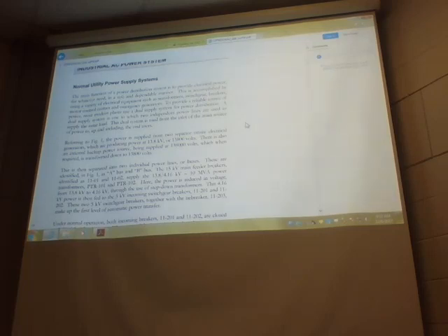So the main function of a power distribution system is to provide electrical power for whatever need in a safe and dependable manner. This is accomplished by using a variety of electrical equipment, such as transformers, switchgear, breakers, motor control centers, and emergency generators. To provide a reliable source of power, most modern plants use a dual supply system for power distribution. A dual supply system is one in which two independent power lines are used to supply the same load. This dual system is used from the inlet of the main source of power up to and including the end users.